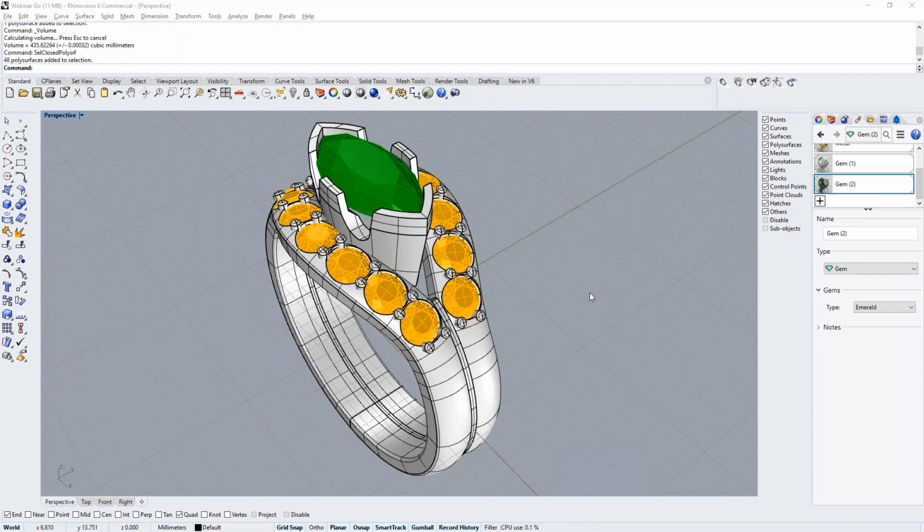Right. Let me add to that. It depends on the printing technology that you're using. The piezoelectric ones that I'm familiar with, and again, SolidScape comes to mind as one of those, I'm spacing out on the other prominent one, but those typically do require one solid closed object. So you would have to Boolean all this together into one object. Interesting. Okay, that's a good distinction on the wax printers.